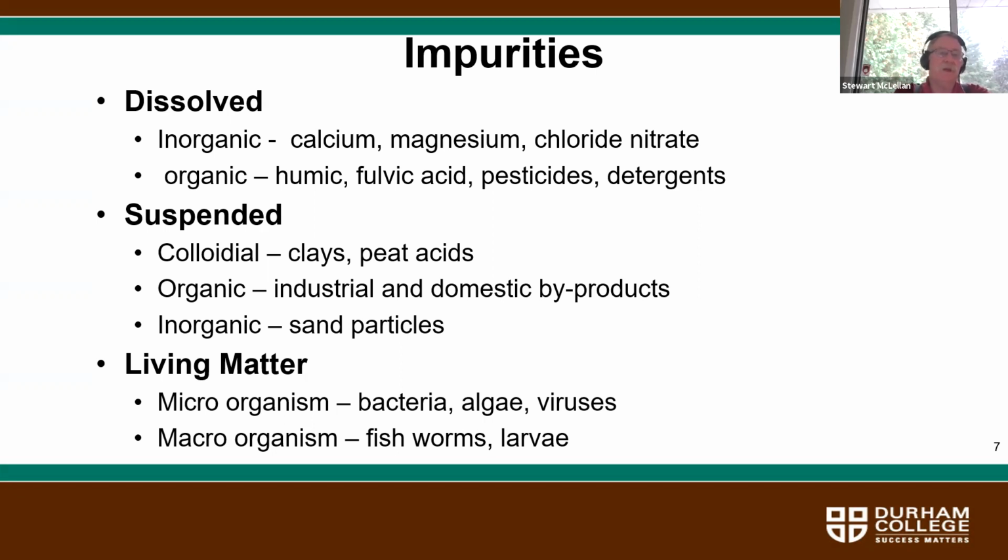Suspended impurities: colloidal, which can be clays and peats. They can be organic, industrial and domestic byproducts. Inorganic, which could be sand particles, and then of course you have your living matter, which is your microorganisms, bacteria, algae, and viruses, and macroorganisms, fish, worms, and larvae.